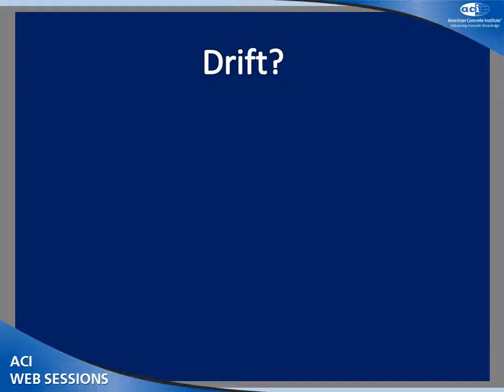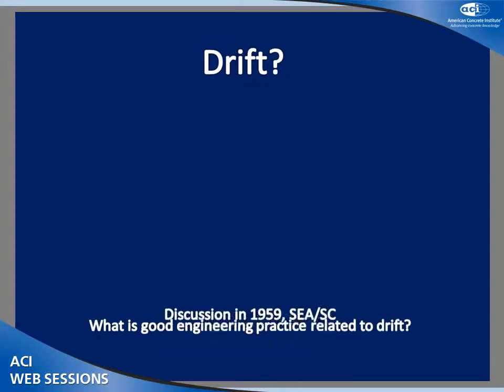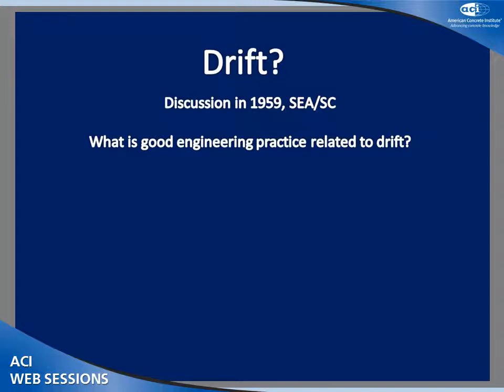Now, to me, although Terry, I think, gave you a very good explanation of it, the interesting part was the question about drift. And if you look at this book today, and it's still worth looking at, you find that there is a tremendous controversy going on in the pages of the book about drift. Because on one side, Nate Newmark starts by saying, I need a ductility of 4. And that means you need a deflection of 4 times the yield deflection at least, if not more. And yet, in other parts, there is no sound.